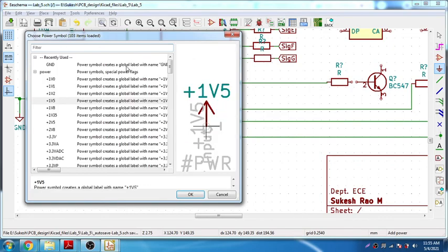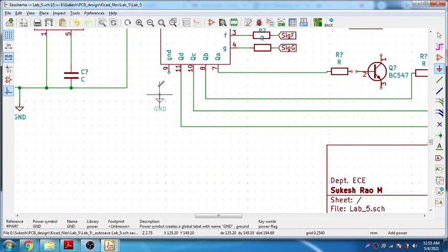That's something very important again, how to match the footprint of all these components. That's why I provided a datasheet for you as well, so you can just go through those datasheets. I don't think you need to add it, the ground is already nearby, so you can just choose it, and pin number 9 you can connect to the ground. Yes, grounding is also done.